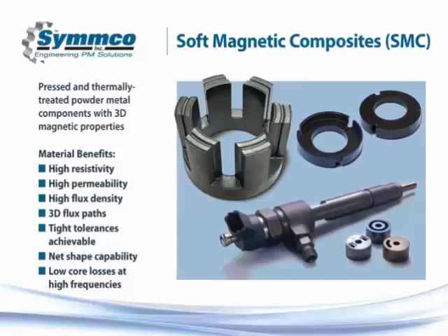So typically in length, in an axial compaction, we're looking at plus or minus 0.003 up to 0.005. On an outside diameter, we're in the 0.0025 to 0.003 range, depending on size. The larger the part, the more the tolerance increases.